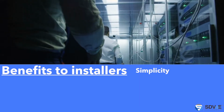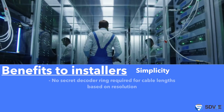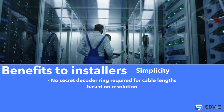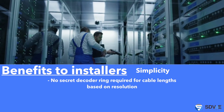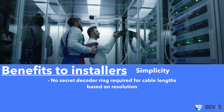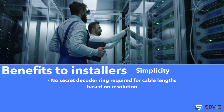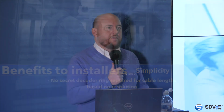Those of you who've installed HDBaseT have tried to read the secret decoder ring that explains what length of cable you're allowed to use depending on what kind of cable it is, depending on what format you're using, what frame rate it is, whether you've got the DSC compression on or enabled or not. It becomes very complicated. And the answer might be 30 meters, the answer might be 150 meters. You need to go read the spreadsheet and try to figure it out.